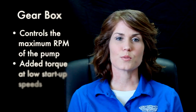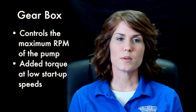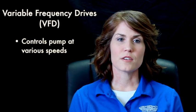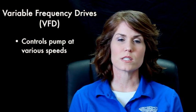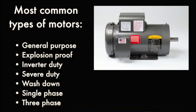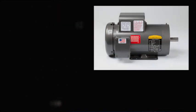A gearbox is required to control the maximum RPM of the pump. It also provides added torque at low startup speeds. VFD, or variable frequency drives, is an option to control the pump at various speeds. The most common types of motors are general purpose, explosion proof, inverter duty, severe duty, wash down, and single or three-phase. Contact us for more types that are available.